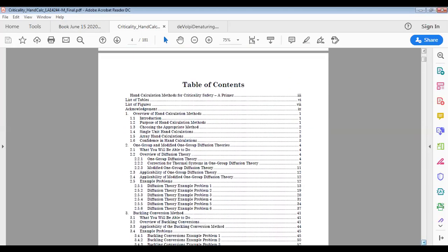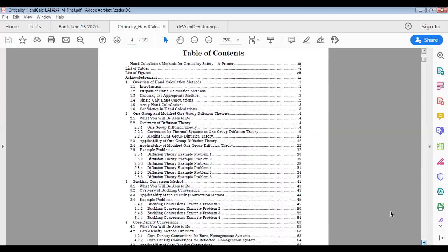Safety is such an important thing. How do you store materials? This is some work that I also did in my career, and I really value these things, especially when I worked in a centrifuge plant. At various stages as the enrichment changes, we had UF6, and you have to decide how to store cylinders. As the enrichment gets higher, the cylinders get smaller, and then the storage in a room has to be done so that the people working there are safe.